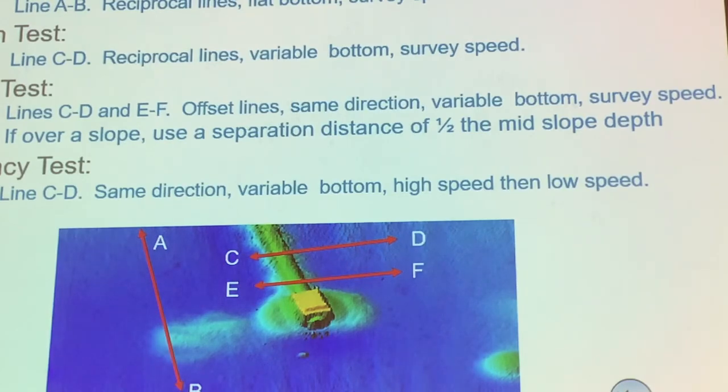So normally for the patch test, what we do is we record the line first. Don't do anything. Once you put the offset, you do your survey, you record all these lines first. A, B, C, D. Sorry, 4 lines. Okay, so for A, for roll, you have to do one same line, go one direction, record, and then do the same line the other direction. That is for your roll.